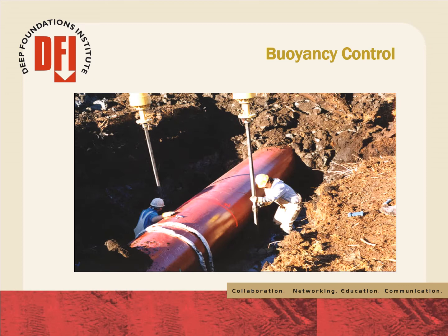Helical anchors are widely used to counteract buoyancy issues for a variety of structures that are below the water table, such as buried gas transmission pipelines, as shown in the photo above, and empty to nearly empty underground storage tanks in high groundwater conditions. They have also been used to anchor plastic septic tanks in situations where the tank, which weighs next to nothing, becomes close to empty and the water table is high and the ground cover over the tank is only 1 to 2 feet.